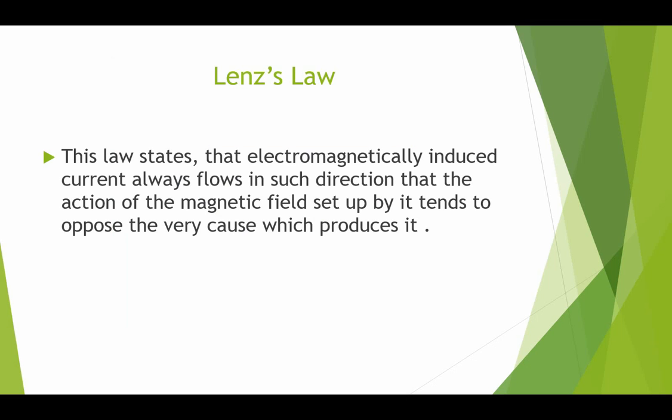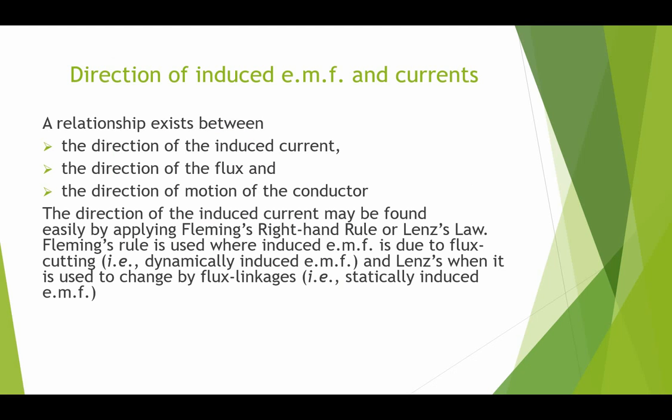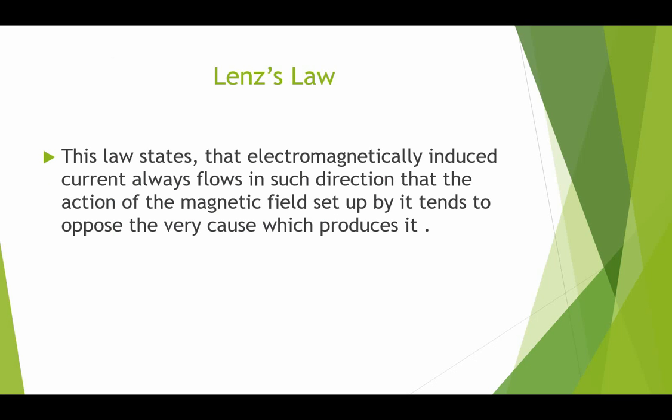Now what is Lenz's law? Lenz's law is also used to find the direction of induced EMF and current when there is a statically induced EMF. This law states that the electromagnetically induced current always flows in such a direction that the action of the magnetic field set up by it tends to oppose the very cause which produces it.